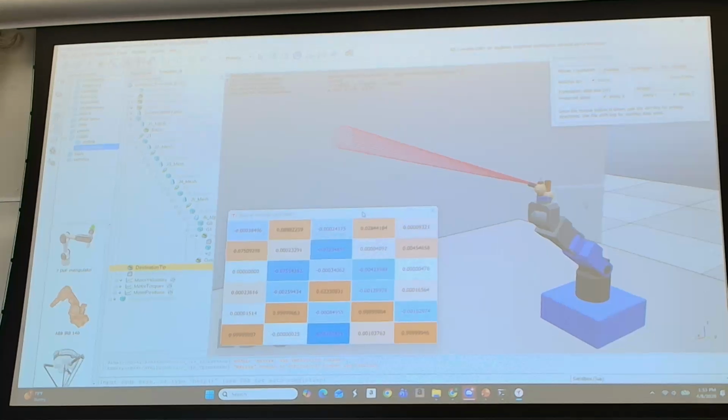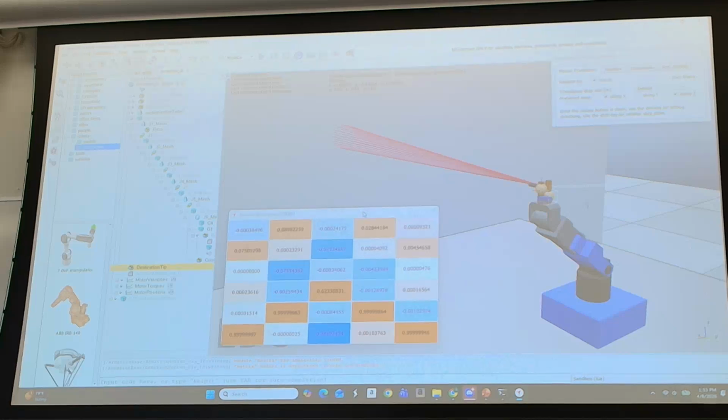So inverse kinematics isn't magic, but when you have a lot of solutions, it picks the best solution, typically from an LMS. We went through the weights and talked about the three approaches that were typically done, as it's trying to find the optimal from the set of a whole bunch of solutions. But if we're in a 3x3 or a 3-joint planar, it's pretty fixed. There's not a lot of solutions.